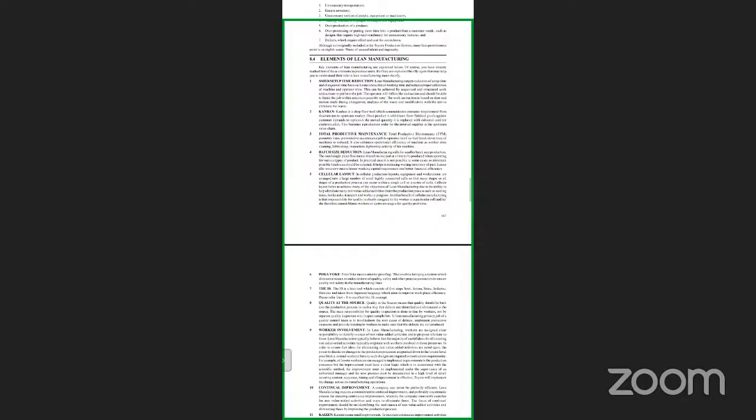And the next one is Kanban. Kanban is a shop floor tool which communicates customer requirements from downstream to upstream workers. Once a product is withdrawn from finished goods against customer demand, the moved quantity is replenished and replaced with a colored card or electronically. This becomes a production order for the internal supplier in the upstream value chain.